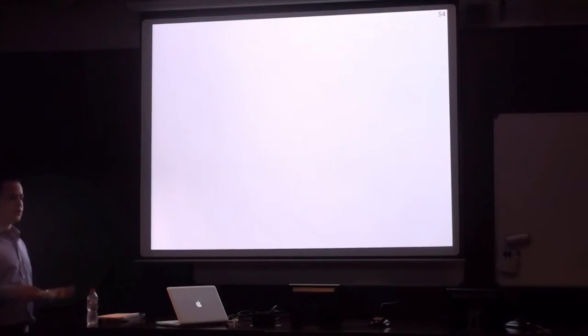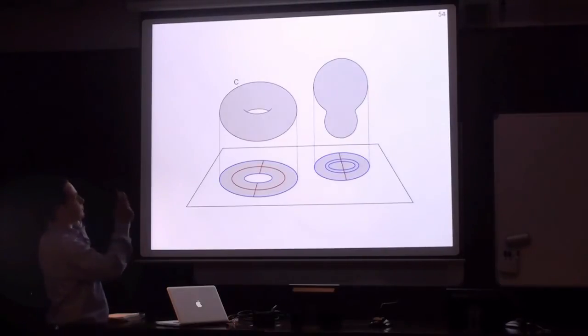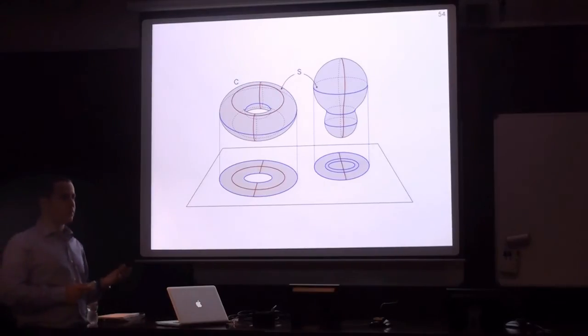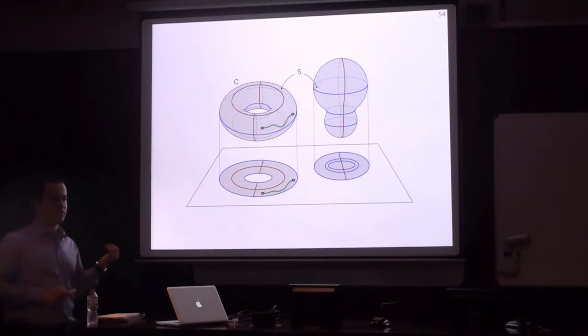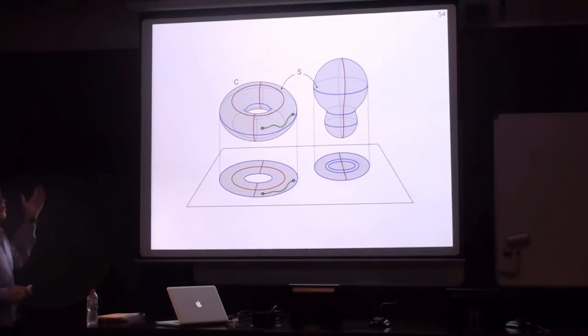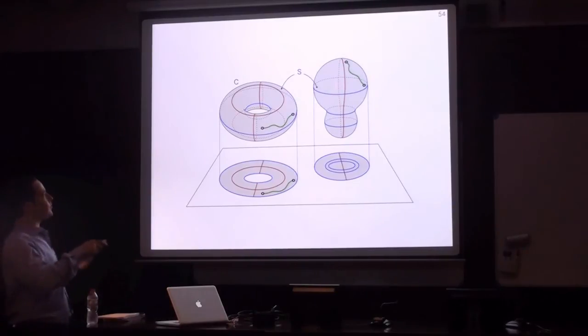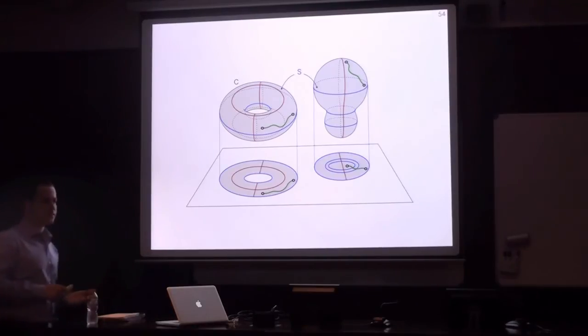With all these previous techniques, we can introduce projections of the singularity sets to the input and output spaces, which provide rich information on the global shape of the configuration space and the singularities. These projections can also be used as safe navigation maps, if you want, because a path in the projection that does not cross a singularity necessarily corresponds to a singularity-free path in the configuration space. But not all singularity-free motions are represented in the projections, as in this example. We have here a singularity-free motion in the configuration space, which seems to cross the singularities in the projection.